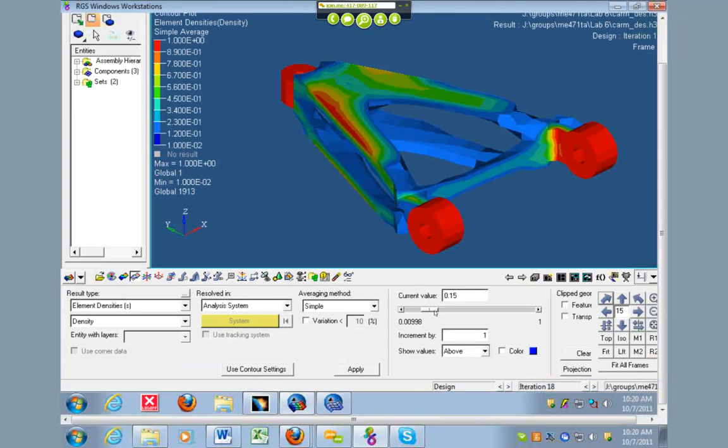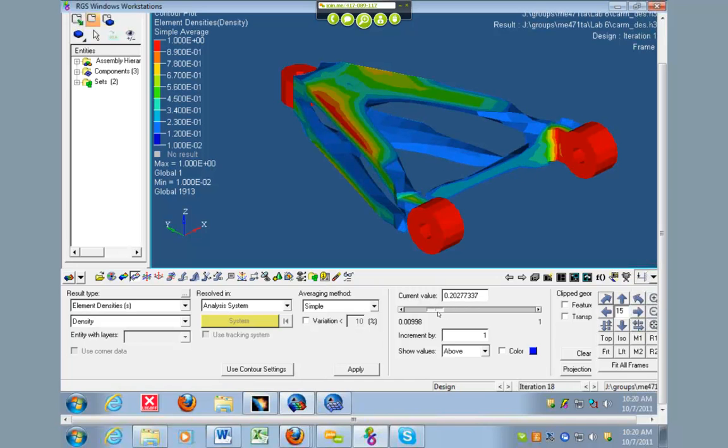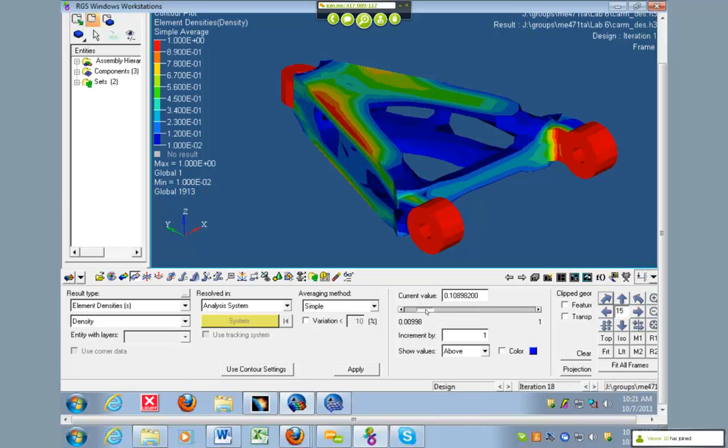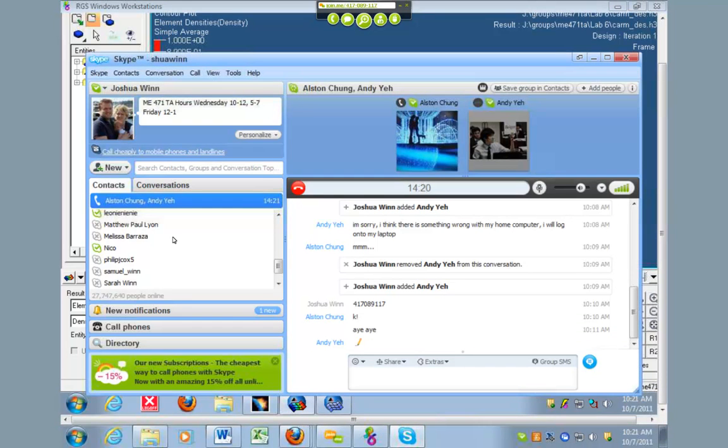Yeah, so as you're coming in here and doing this, that is not going to work because there's no geometry here or down here. So you just need to put this where, okay, I've got geometry. It doesn't look like there's a lot of material where there are gaps. But yeah, you should use your best judgment there. You want to make sure that anywhere there's red, you're not removing material from that, because red is high stress. So that's actually probably a place where you want to put more material rather than less. Okay? So you just do the best you can to estimate where that is.